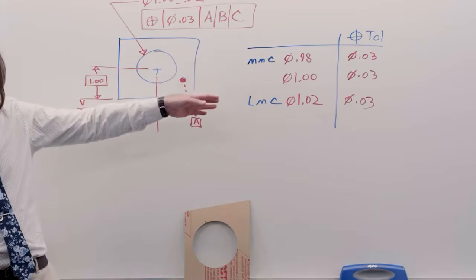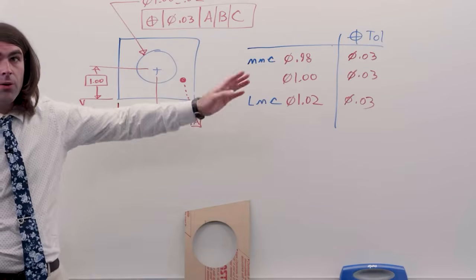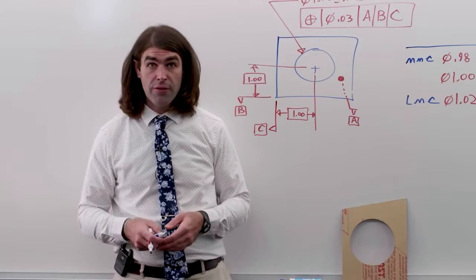Comes in the middle, 30 thousandths position. Comes in at LMC, the largest hole, 30 thousandths of position. Okay, so pretty straightforward stuff.